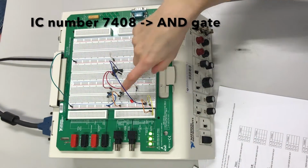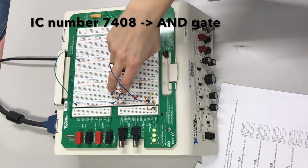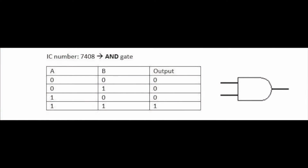Next we used the 7408 IC. Now we had to push both buttons to get a positive output. In the truth table it can be seen that the gate is an AND gate. For an AND gate, the output is true when both inputs are true, otherwise the output is false.